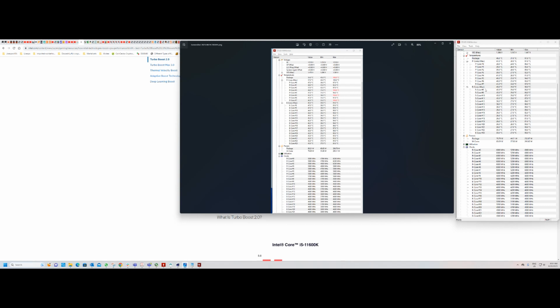But thanks to undervolting, I was able to set up my temperature and finally get this below 50 degrees, even under no load. I was able to at least get this in a stable condition here. And again, with lower voltage as well, and able to overclock it with all cores as normal here.